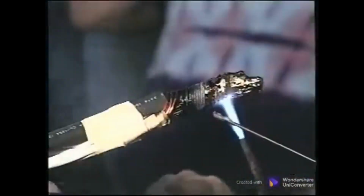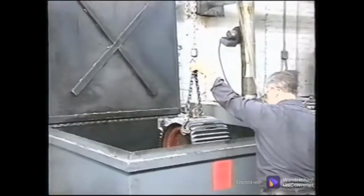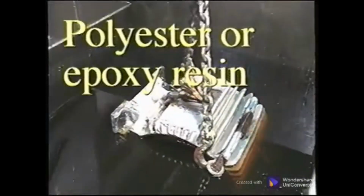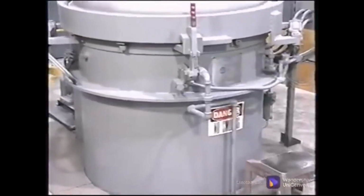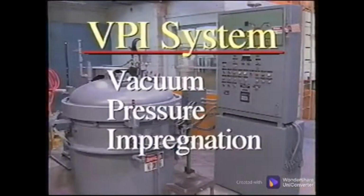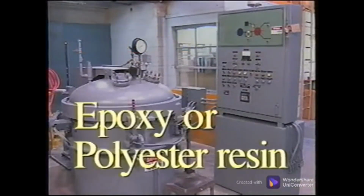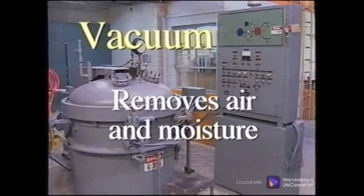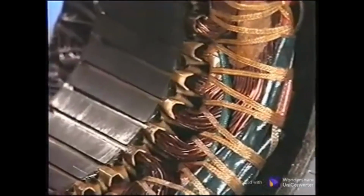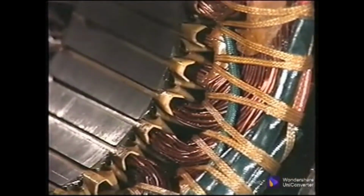The ends are tied together to hold them in place, and the entire stator assembly is tested before being heated and then dipped into a varnish vat that insulates the individual components and stiffens the stator assembly. Another method sometimes used to insulate the stator is the VPI system. It is a vacuum pressure impregnation process using an epoxy or polyester resin mix that is heated. A vacuum is drawn to remove air and moisture. Then the stator is flooded with the resin, forcing it into the stator using pressure. The epoxy is baked on to all the surfaces, forming a rigid stator assembly.